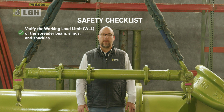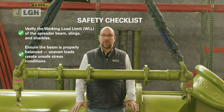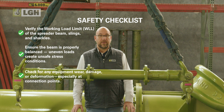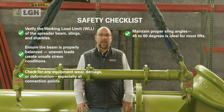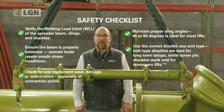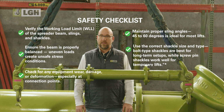Verify the working load limit of the spreader beam, slings, and shackles. Ensure the beam is properly balanced. Uneven loads create unsafe stress conditions. Check for any equipment wear, damage, or deformation, especially at connection points. Maintain proper sling angles. 45 to 60 degrees is ideal for most lifts. Use the correct shackle size and type. Bolt-type shackles are best for long-term setups, while screw-pin shackles work well for temporary lifts.